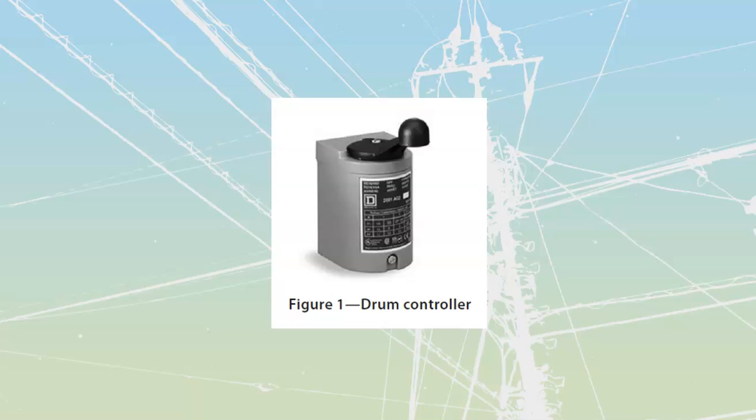Let's start by talking about manual starters. All that a manual starter does is it starts and allows the motor to accelerate. It says in your book that it starts and accelerates it. It's the actual motor itself that is going to cause that acceleration. They are going to require human operation of a switching device to control the energy that we're going to send out to it.